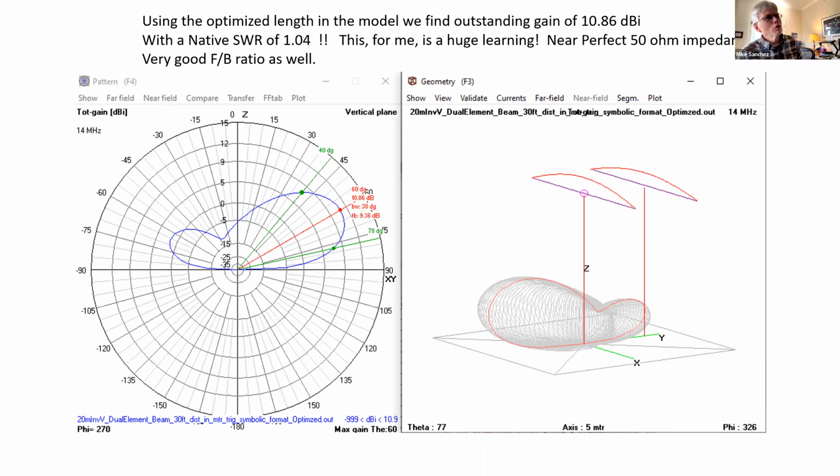Well, I choose dBi only because it defaults to that, and it was a good year before I knew I could change it. By then I was used to dBi, and I always use over ground, because I just don't know why you would build a bunch of simulations in free space, because you're never going to build an antenna that you're going to use in free space.